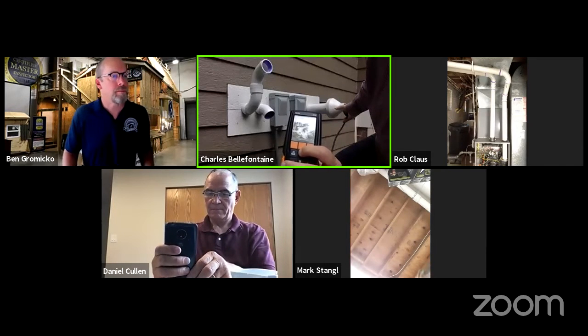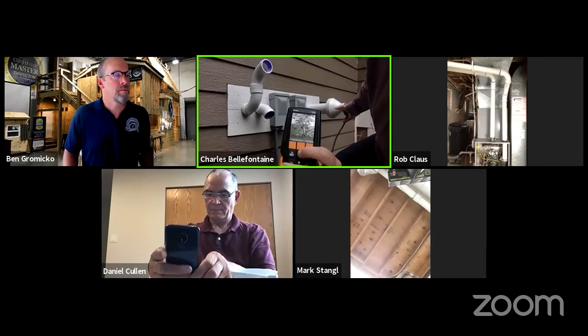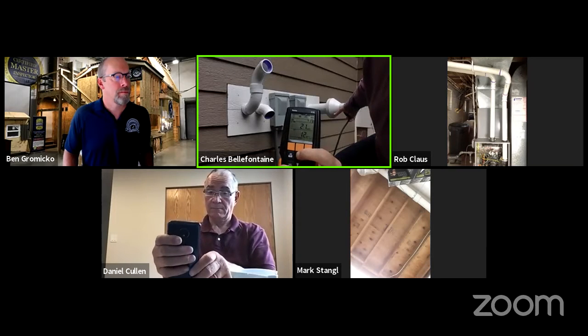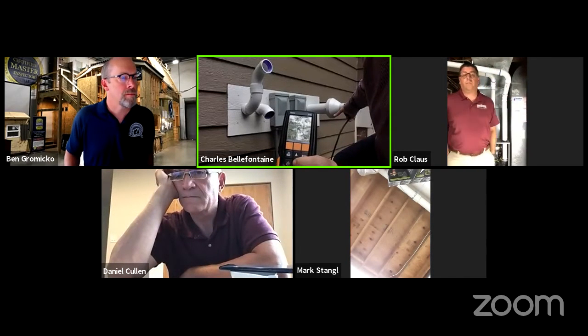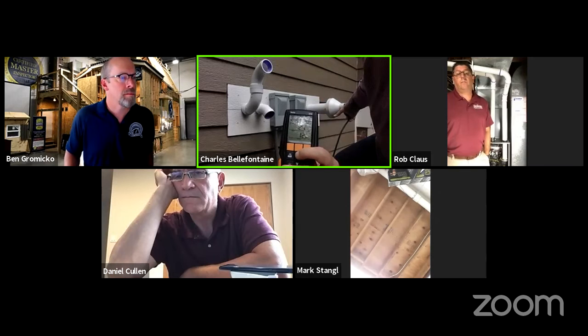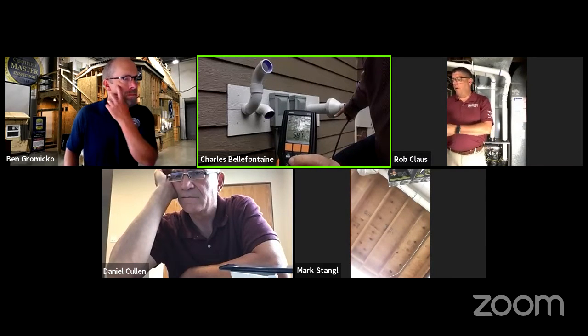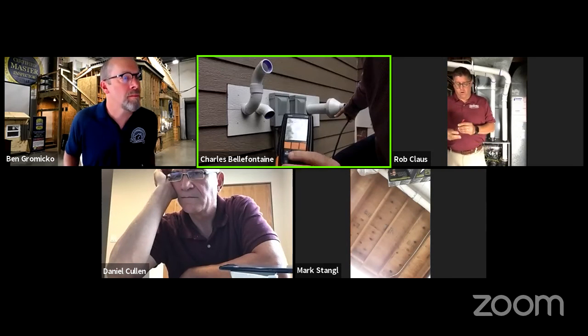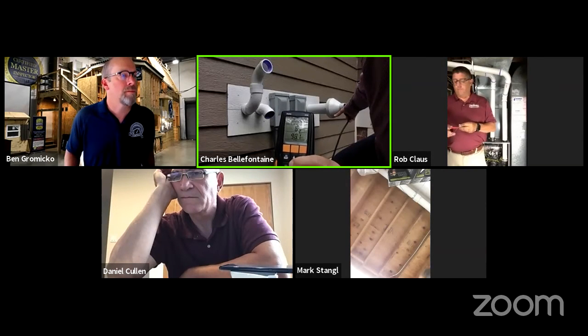So we scroll through back here. And the top number now, that 21, is showing my air free. So that's calculating if this furnace was in a 100% oxygen environment, it would be producing 21 parts per million of carbon monoxide. So we'll leave that back at the oxygen. This can also calculate and tell me exactly what efficiency we're running at. So this thing says 98.1. So it's running nice and clean.